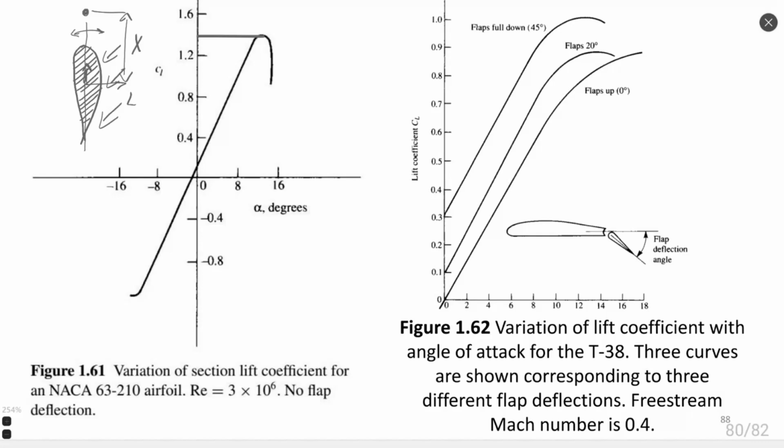And the drag is something that must be taken into account in the force balance. Thrust, which acts in the opposite direction, must be much bigger than this drag. Of course, this drag is very small at fins. It's very small for airfoils, right? And usually thrust is a much bigger force. And the most significant part of drag is created by the head of the rocket itself.